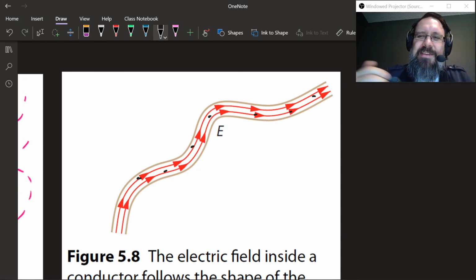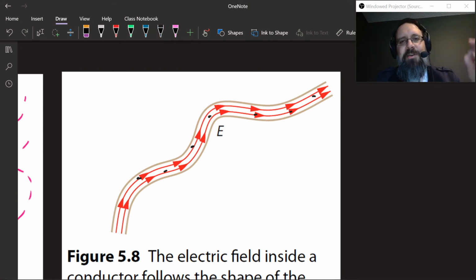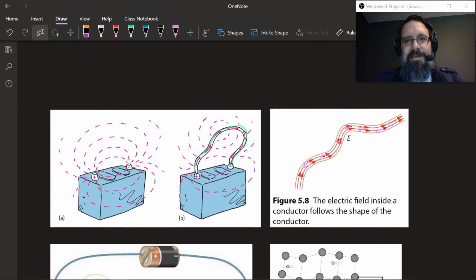And so it's sort of like a misconception. It's not like an electron is hanging out over here and moving through the circuit. That's not what electricity is. What electricity is, you immediately establish the potential difference and then boom, this electric field is everywhere in the conductor, and then every single one of these charges, I guess I'm having them go the wrong direction because they're electrons. Electrons go opposite to the field. And then every single one of these electrons will start to flow because every single one of these electrons has a force on it from the electric field that was established by the potential difference.